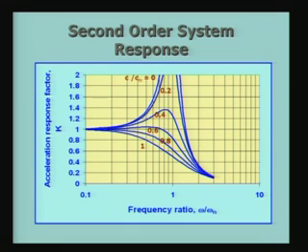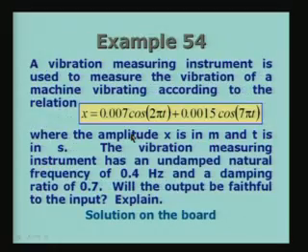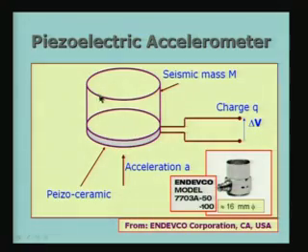For the acceleration measurement, as you have already seen, we should be in this part of the curve, so that you have a good faithful response with respect to the acceleration. So, we have some idea about the vibration transducers, and let me just look at one more which is very popular. It is called the piezoelectric accelerometer, and the principles are exactly like what we just now discussed.